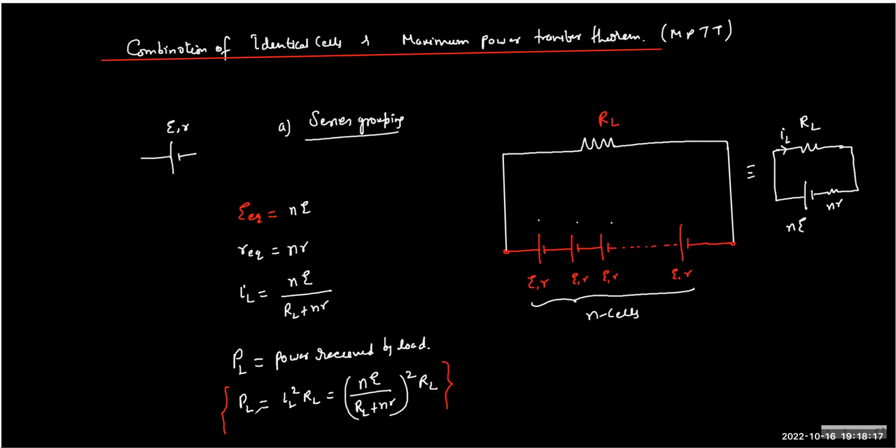Tending to zero. Now, why are we going to create a circuit with no consumption of power? We know that we have so many cells, so we can have sufficient energy to be consumed. So a load with almost 0 resistance will not do justice to the circuit made. I will not connect such a resistance because it will consume nothing. Most of the energy that the cell will develop will be consumed by the internal resistance of the cell itself, which is not a good idea.